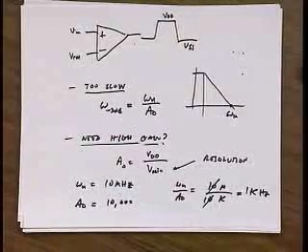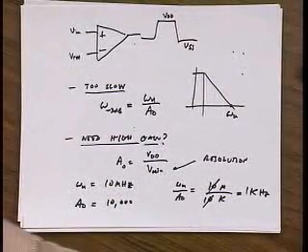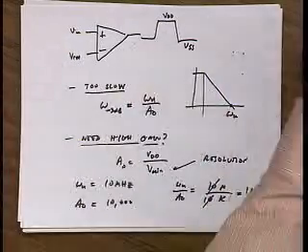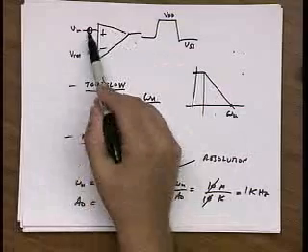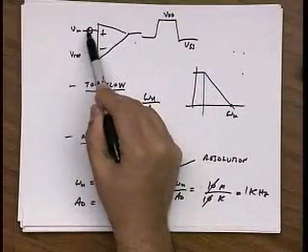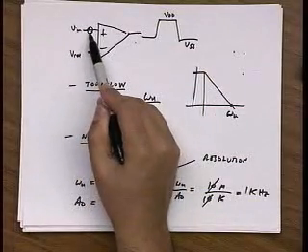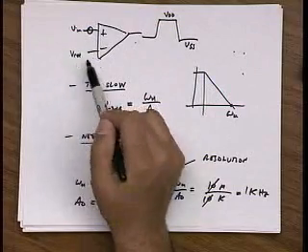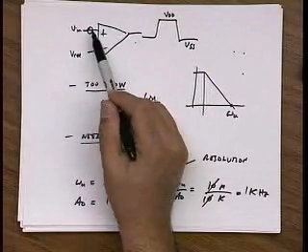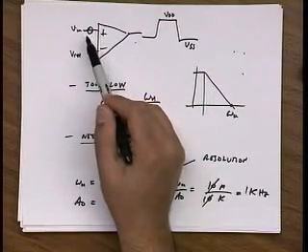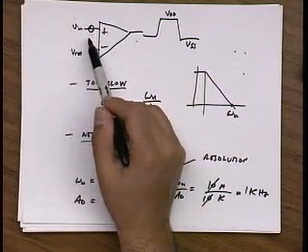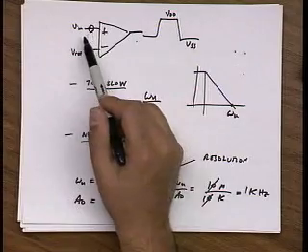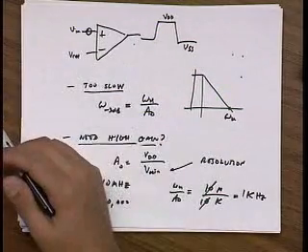Debo? Limited by the offset voltage? Yeah. Remember, the way we modeled this is we put an offset voltage in front here. If this offset were a fixed number, I could just change my reference by the offset. But it's random, and all I know is its mean and its standard deviation. I know the mean is 0 and the standard deviation is 10 microvolts.